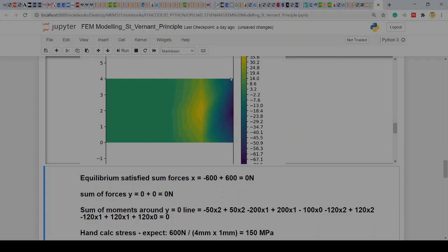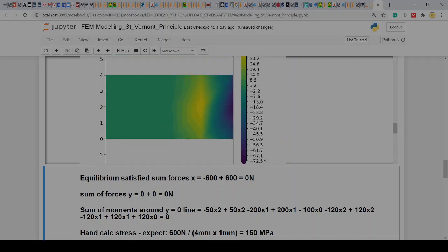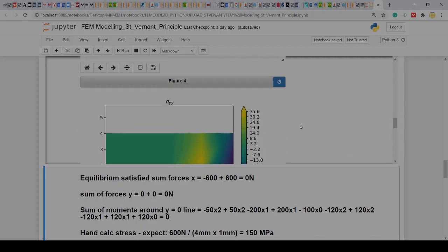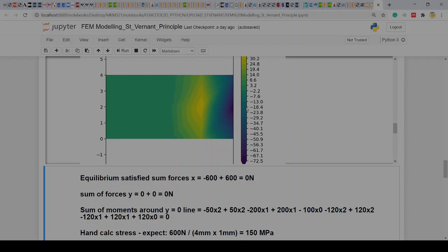On this edge here though, quite a large variation of stress of minus 70 around this edge. Okay, so then some compressive stresses that we see here. You can nicely see this development of the stress field inaccurate, and getting more and more accurate as we get in. All of a sudden, far enough away from this, we start to get quite accurate.